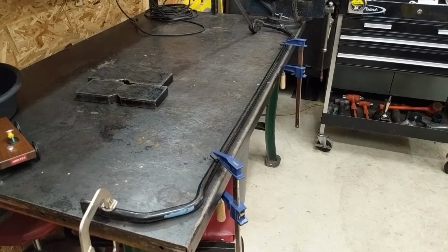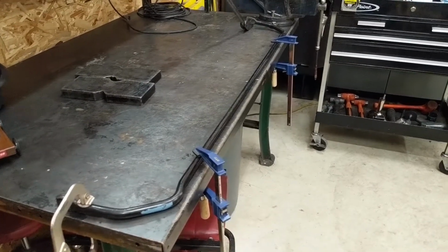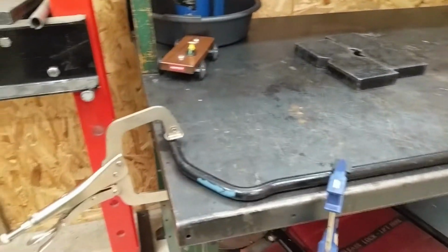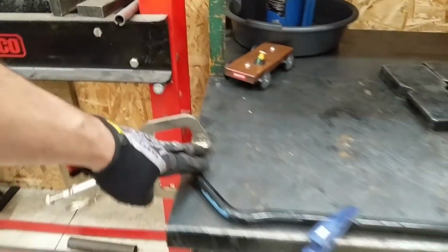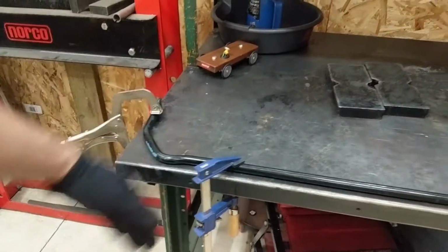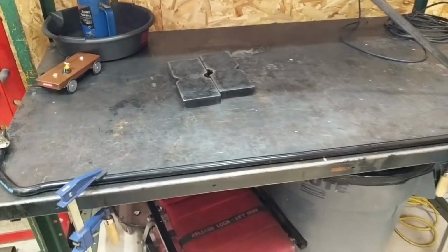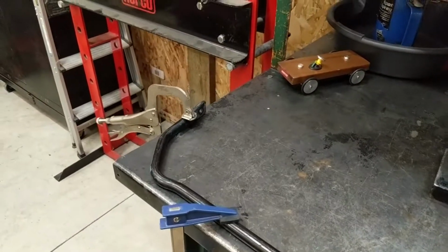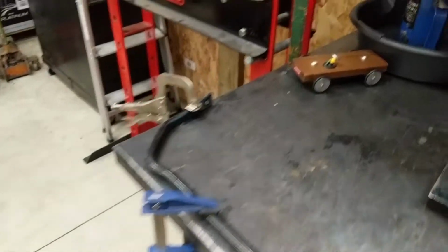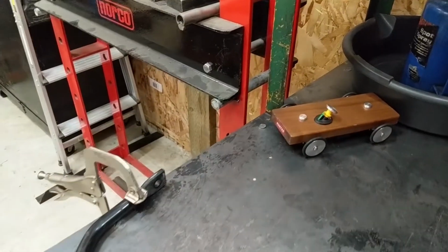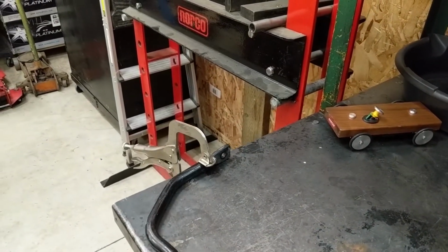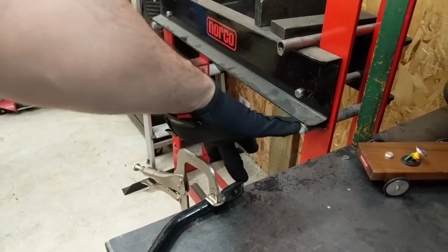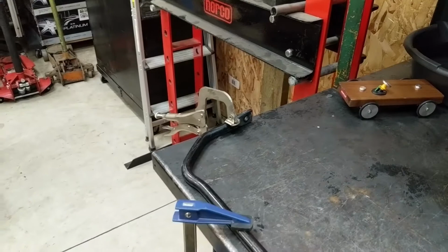I'm going to show you an example here of the forces that are typically acting on a sway bar. The end of the sway bar that curves outward from the long part that spans the width of the vehicle, on each end there's going to be a portion of it that sticks out, usually about 90 degrees to it. And the end is where the end link is going to connect it to either an axle or the suspension component that's moving, or to the chassis. So this part is supposed to be acting on the link, resisting the movement.